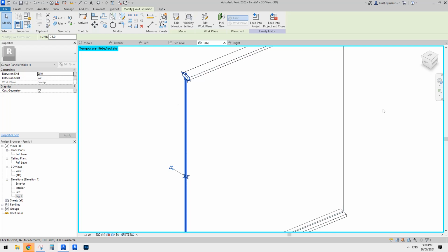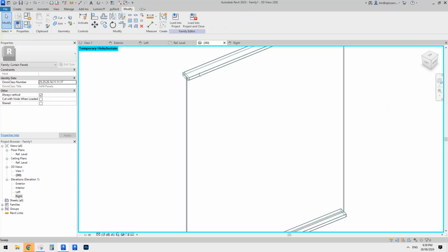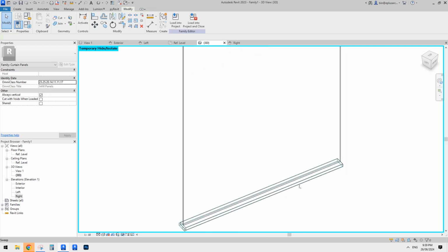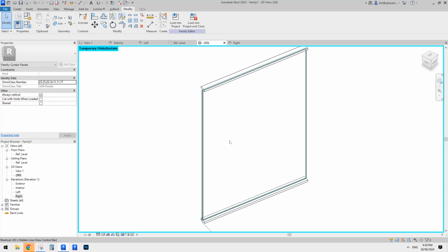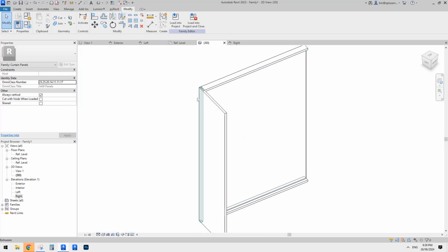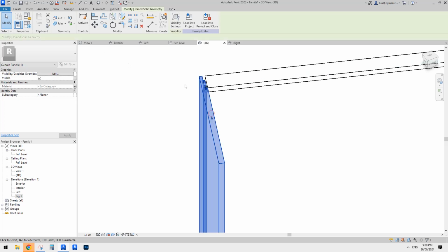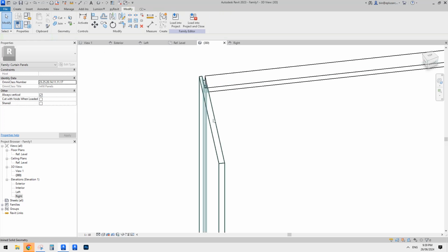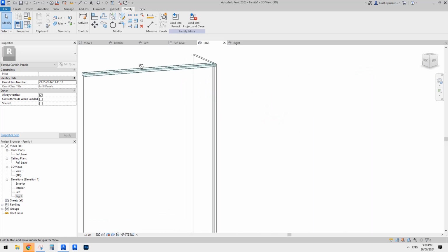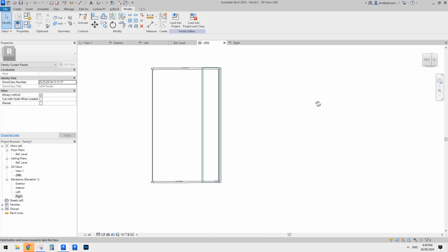So now if I click anywhere here, it will automatically cut this, and this. So let's have a look. Bring back the other mullion, HR. It actually also cut this one. So we don't want this void to cut this. So we can use cut and uncut geometry. Click on this void and click on this solid. Okay, and then we have everything we need.